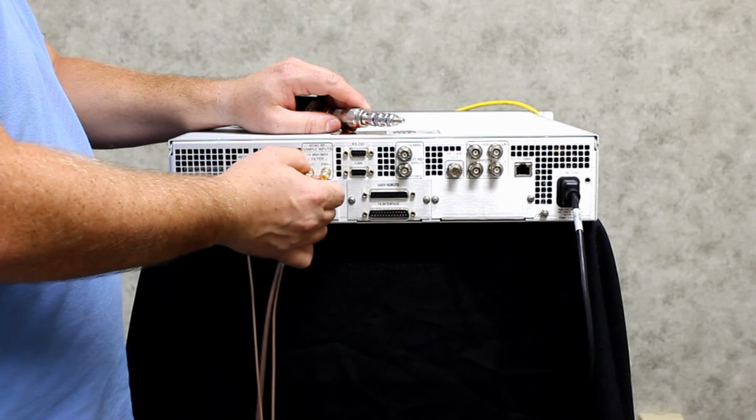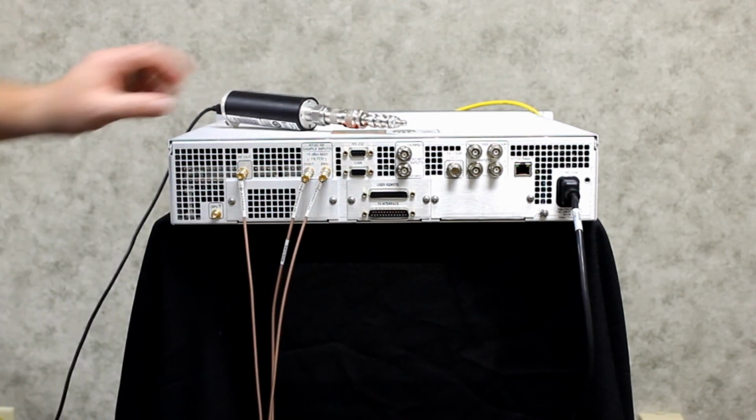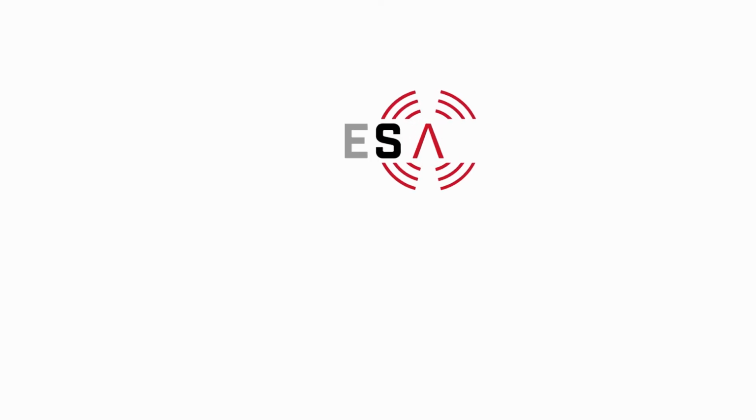And we've finished our alignment procedure. Both of our samples are within 1 dBm of minus 5, which is right in the ideal range for the M2X exciter. This concludes our instructional video.